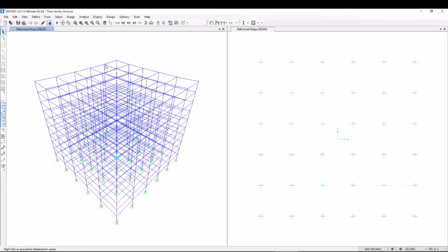Now we can see from that self load some deflection quite less, and I can go to check millimeters during that self weight. We can see this node. Let's see if we can get this. So this point is about in the z direction less than 1 millimeter.